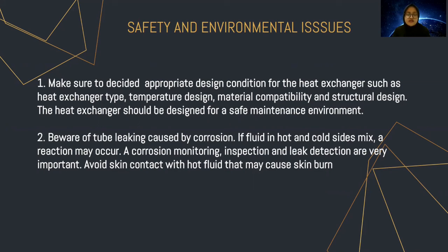The heat exchanger should be designed for a safe maintenance environment. Second, beware of tube leaking caused by corrosion. If fluids on the hot and cold sides mix, a reaction may occur. Corrosion monitoring, inspection, and leak detection are very important. Avoid skin contact with hot fluid that may cause skin burns.